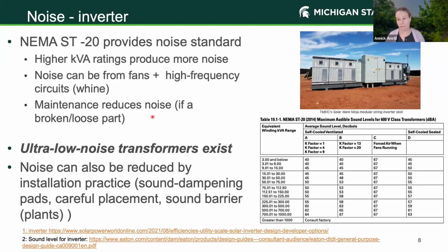So I'm mentioning it here because in Michigan it's becoming an increasing issue in terms of noise. There's been quite a bit of complaint about it because of a certain choice of inverter. But again, you can choose or ask for transformers that are lower noise, because as we build bigger capacity farms, there's more chance that those larger inverters, depending on how many you have, will make more noise.